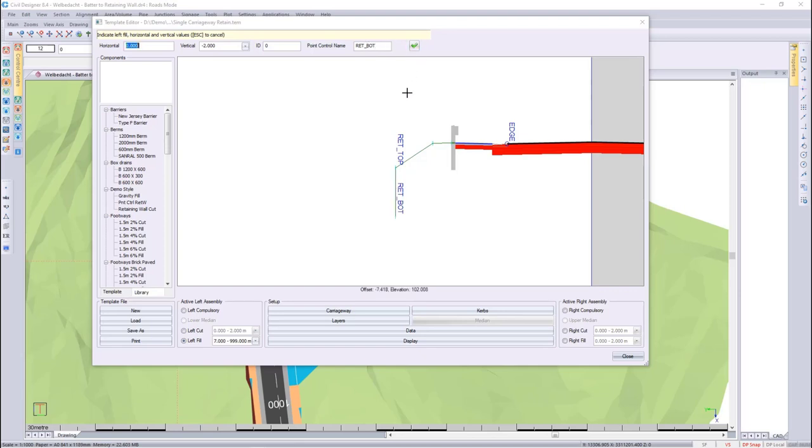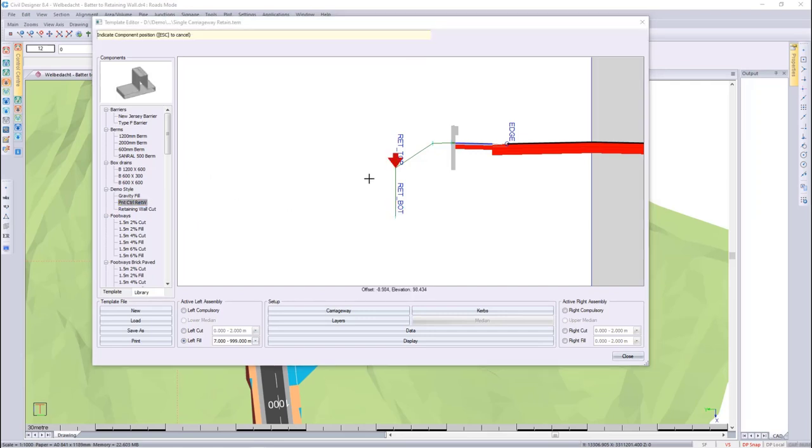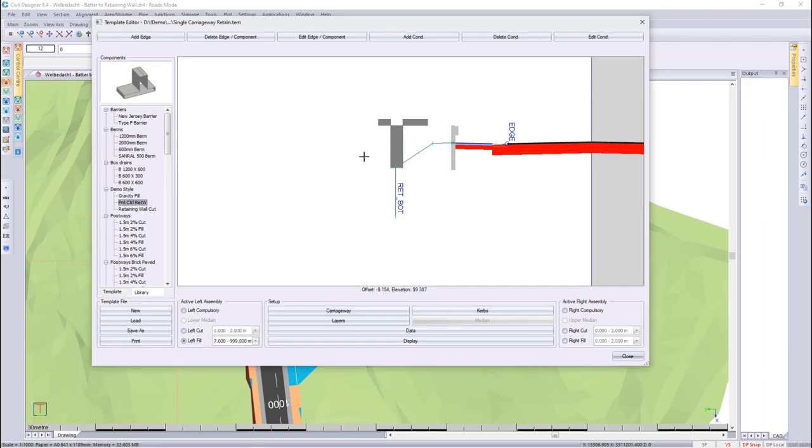And escaping. For the retention wall, I've created something specific for this project for a reason. Now, if I place this, you'll see that it looks like it's inverted, and I've left it like that for a reason so I can explain to you. It may be that you're in the same situation and it looks inverted. I'll show you how you can fix that.